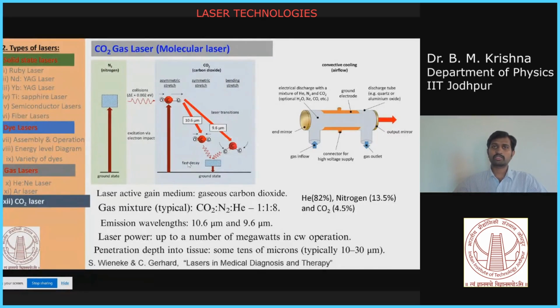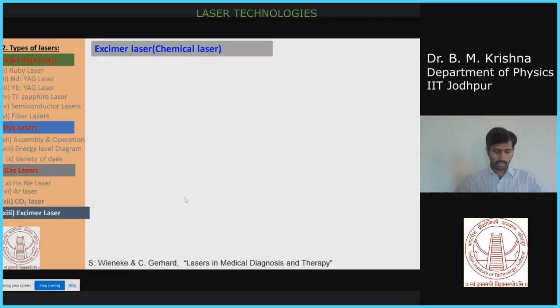You also heard about pulsed laser deposition. Many material scientists generally use this technique called pulsed laser deposition. In that case, you need to use a high power laser, where generally the CO2 laser is a better fit. They use it to coat any material, like if you want to coat silver ions or any metals onto your substrate. So you come with a high energy, you rip off the atoms from your metal, then you deposit them onto the substrate. For this kind of method, generally the CO2 laser is a better fit because of its high power. Okay, so now we move on to the Excimer laser.